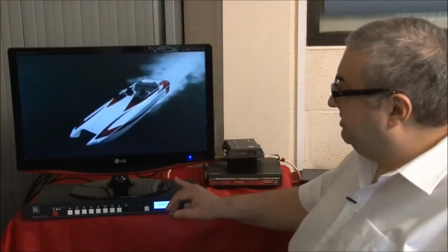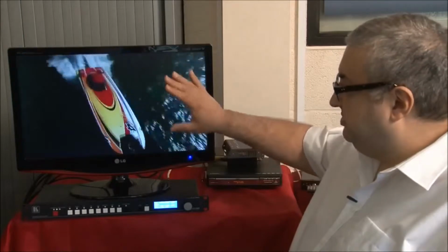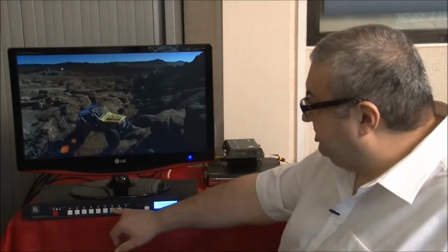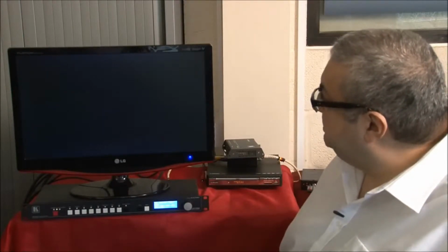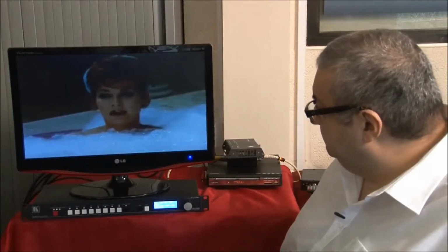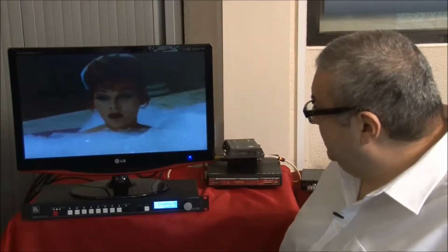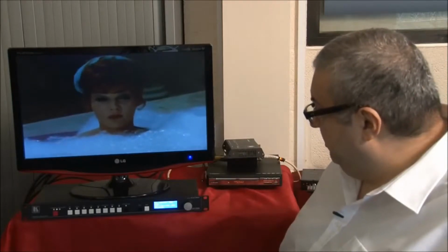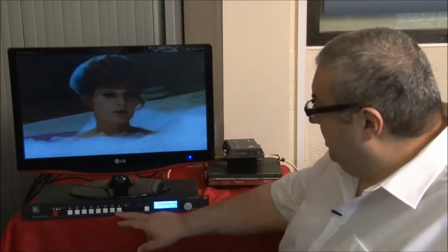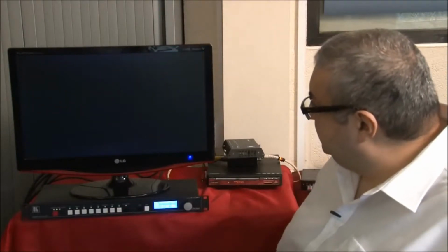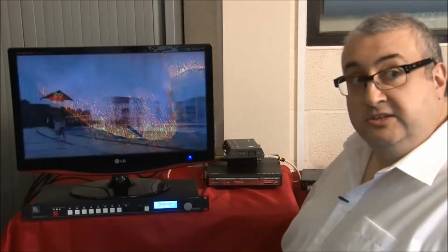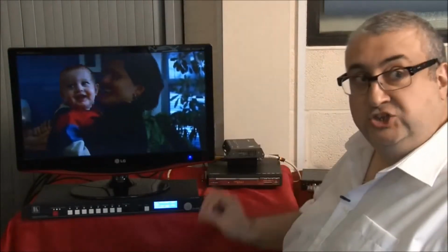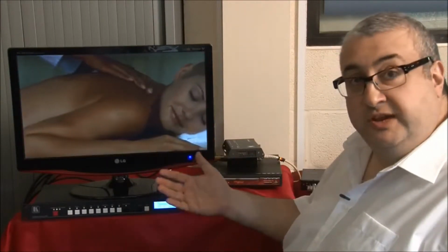So I'll just demonstrate. For now I'm in LED mode, I haven't resized, you've got a full screen picture. I'm currently showing HDMI, and when I switch to composite video, it seems to take quite a long time and the picture will not be clean. So we've gone to the other input channel here. We're now on composite video. And if I go back to HDMI, you see there was a flash. That was the scalar resyncing to maintain low latency. So the switchover wasn't clean. We got a flash or a glitch changing between input channels. How bad that appears depends on the monitor or the LED screen or the projector.